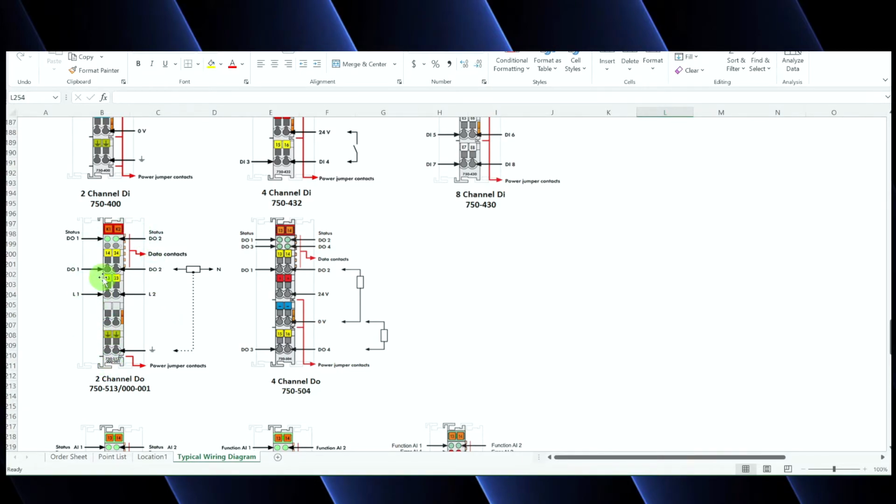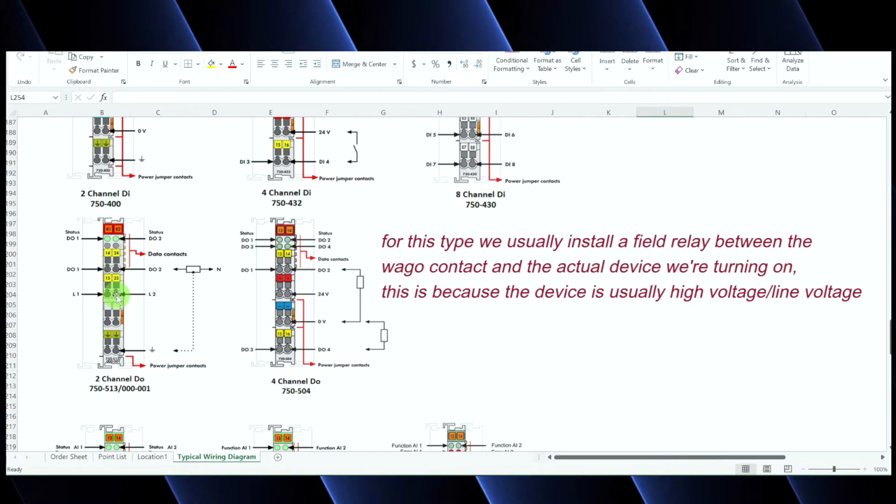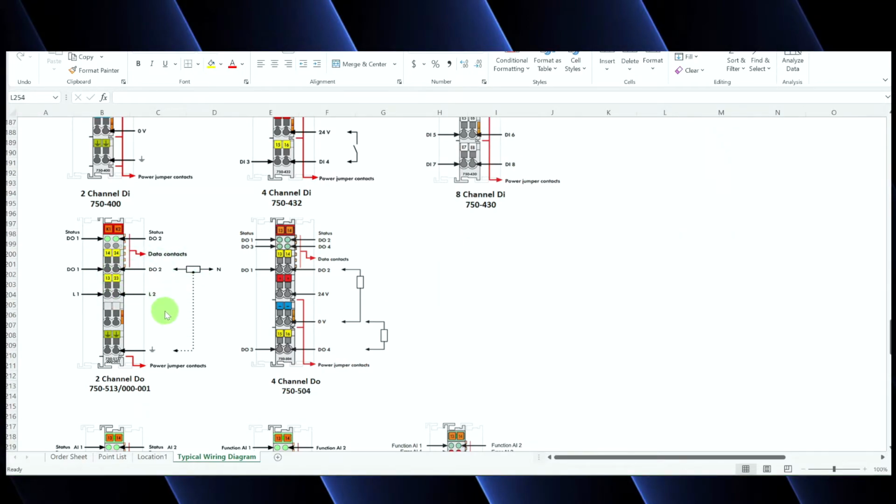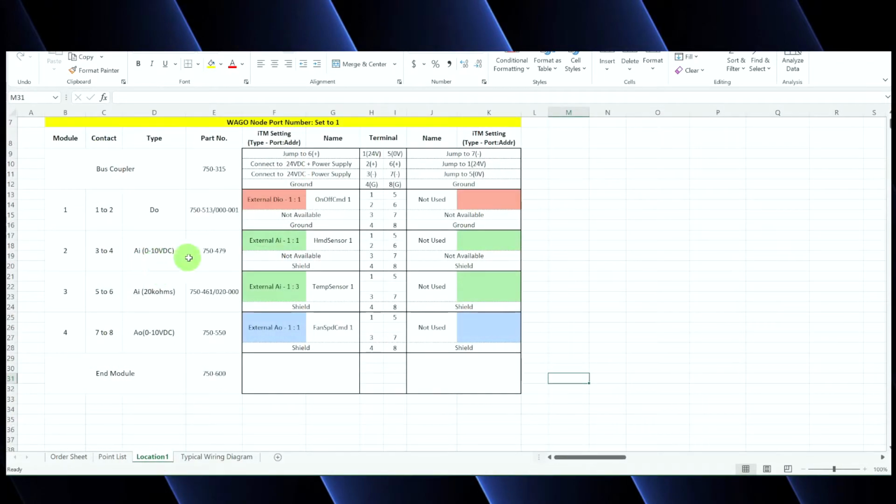And it's pretty easy. You just basically have your 2 wires that are going to basically close a contact on whatever device you want to enable or disable. And then if you had a second device, the right-hand side of this contact, this would be channel 2. So DO1 and DO2. That one's a pretty easy one. So once we've got that wired up, we're going to go ahead and go to the next device that was on our list, and that is our AI analog input